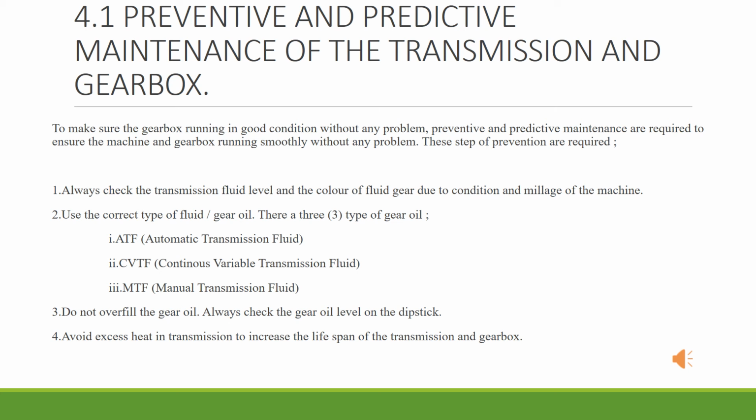The third is do not overfill the gear oil. Always check the gear oil level on the dipstick. The fourth is avoid excess heat in transmission to increase the lifespan of the transmission and gearbox.